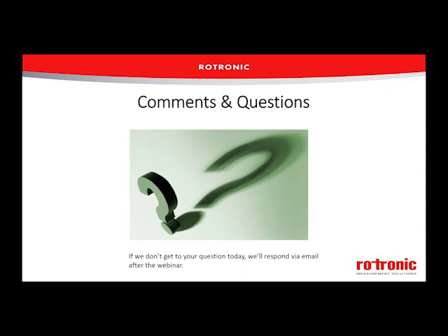That's a very good question. It comes down to what you need out of your uncertainties. The temperature stability will affect the uncertainty of your measurement. So you need to look at what your required uncertainty is for this calibration point, and from that, look at what you need from your temperature stability.